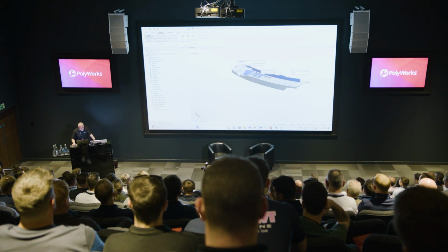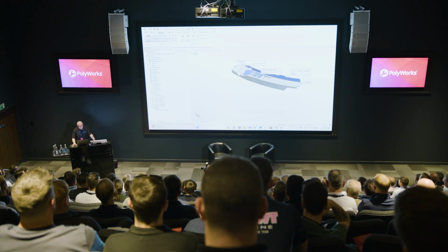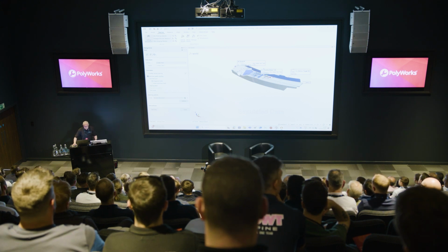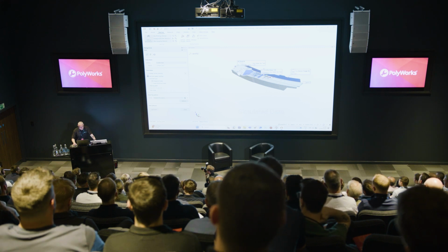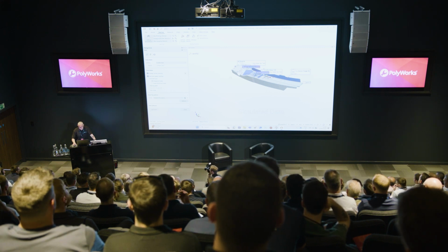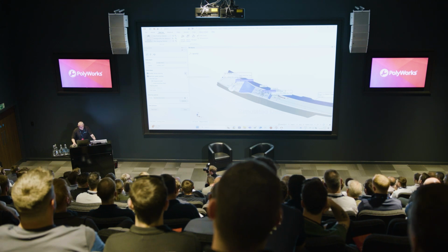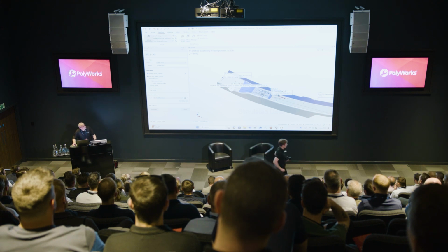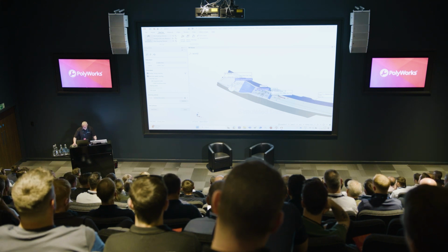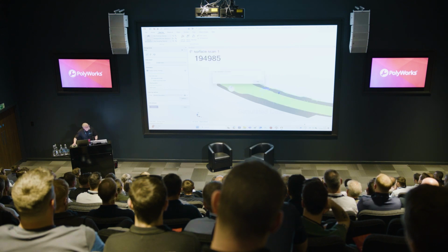Yeah, so I'm going to connect to the devices if I'm connected to the arm, and I'm going to start the scanning. So this pre-alignment works if I'm doing a surface scan or a surface and boundary scan. This is the new button I've got here: pre-align during scanning. If I tick that on, I then go to this defined scanning pre-alignment guide. I need to pick a point for where I want my first scan line to start, and then I need to give the direction in which I'm going to scan from that point. When I'm ready to scan, I can just hit start scan.